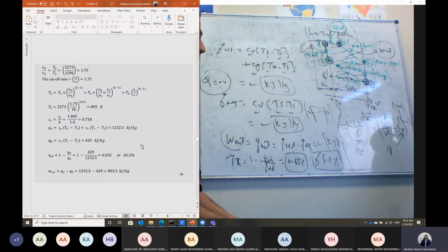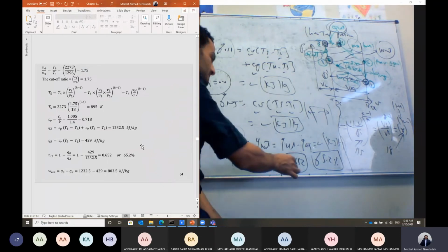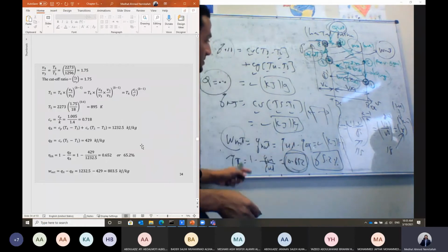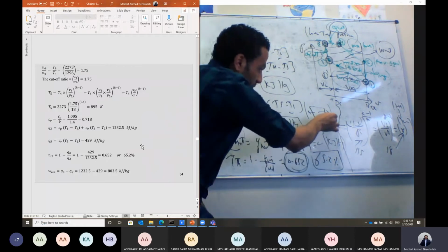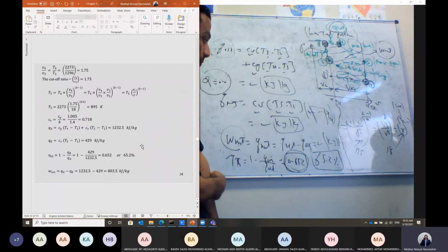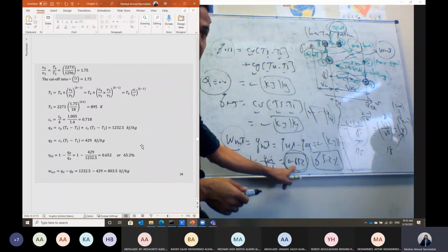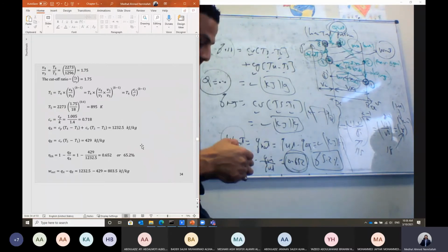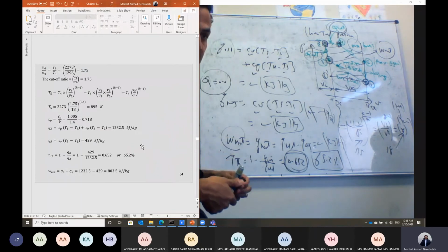The efficiency takes another 1/3, and the third 1/3 is the power output. So here, because the calculation does not account for the heat transfer to the cooling water and the lubricating oil, the efficiency is almost doubled. But in reality, we have to have some heat rejected.